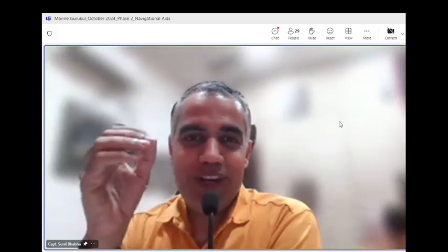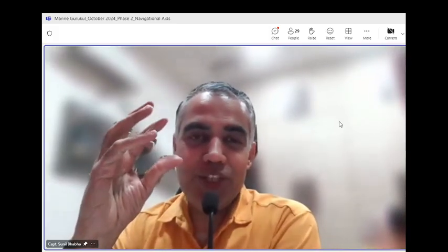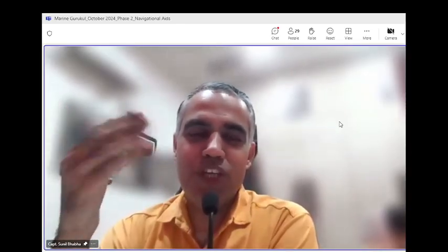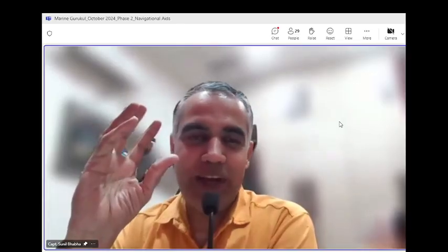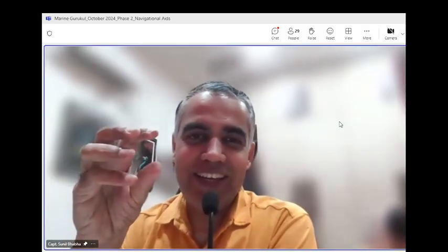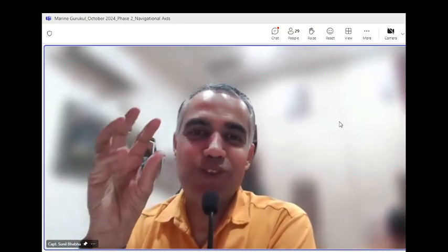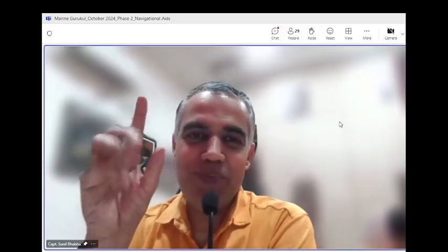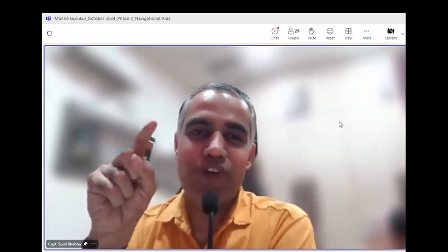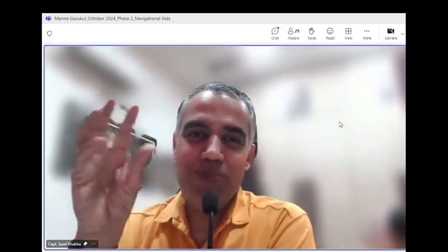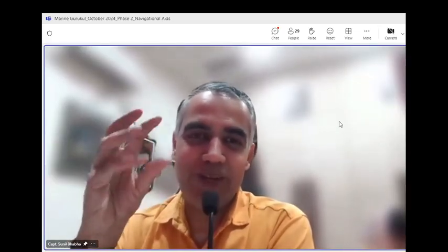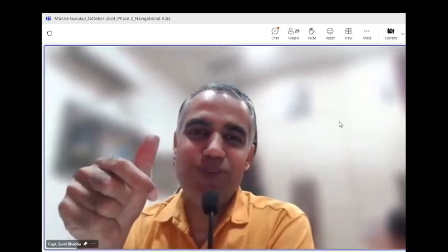Now beta, we saw that the Earth's magnetism is affecting our ship in different ways. So ship's magnetism is changing continuously as you move from the equator to the poles, and you change your latitude, you change your hemisphere, ship's magnetism is going to change. Now beta, to correct this, the corrector that we will fit, that corrector will also be a soft iron corrector. So this is one of the principles which we follow in magnetic compass correction. A soft iron deviation is corrected using a soft iron corrector. So when the ship changes its location, the corrector, which is a soft iron corrector, is also being affected by the Earth's magnetic field, and its correction will also change.